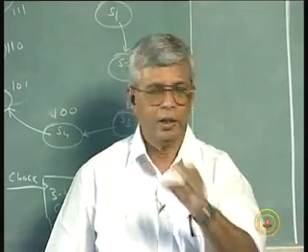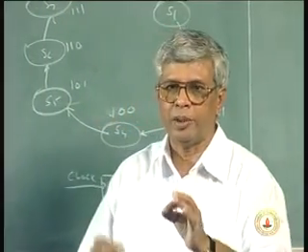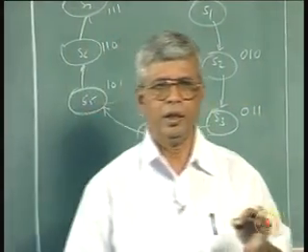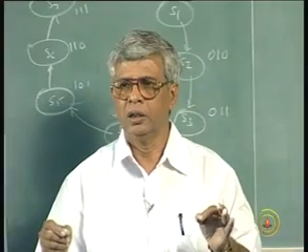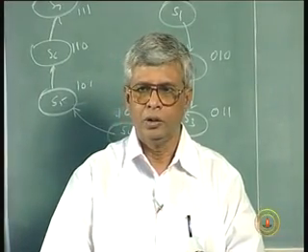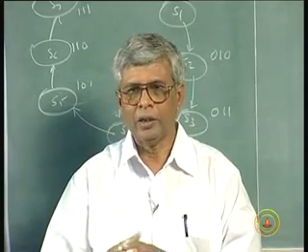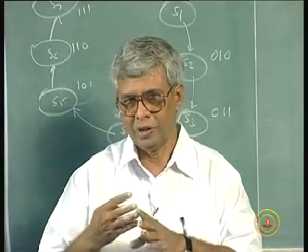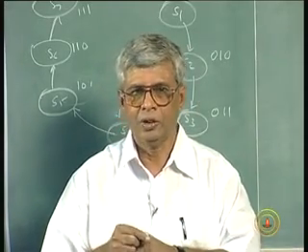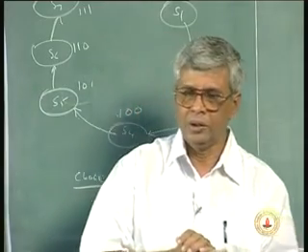Each state, my clock period can be so slow, let us say I want each of these states to be 30 seconds, because states are both of equal importance. So every 30 seconds it will change. In principle, of course, you don't do a 30 seconds clock. You'll have to get a faster clock and reduce it. I told you how to do that.